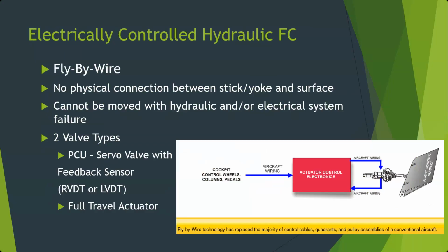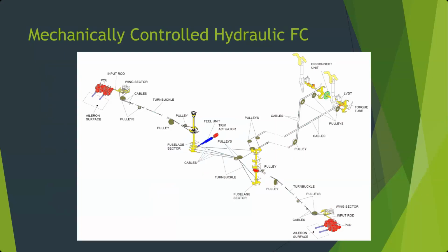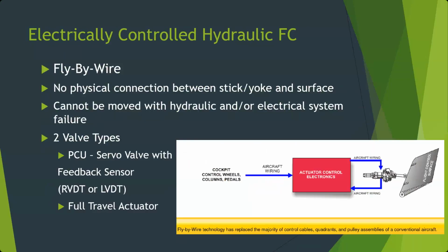And fly-by-wire, don't confuse it with fly-by-cable, okay? Fly-by-cable is the cables that actually physically move the valve, push, pull. Well, cables can only pull, but they're run in a pair, so they can pull, okay? Fly-by-wire is electrical wires. So we're sending electrical signals. We're creating an electrical signal at the input, and then we are feeding that into an electrically operated valve to move the flight control.